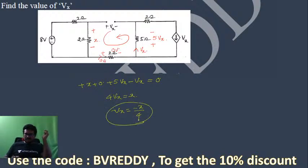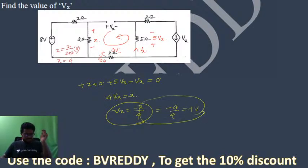The X value we should get first. The X value is this voltage, given as 2 by 2 plus 2 into 8. So this X value is 4. From this, Vx is minus 4 by 4, which is equal to minus 1 volt.